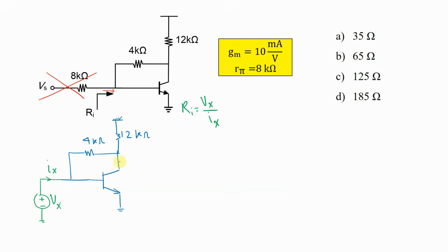Now I'm going to use small signal parameters and show them in this circuit. If you remember, for this bipolar transistor we have this small signal behavior. This is R pi, this is V pi, and this is gm V pi, if we neglect the channel length modulation, which is nothing about early voltage or ro for this transistor. This is our base, this is emitter, and this is collector.